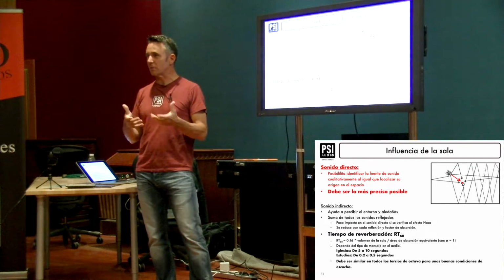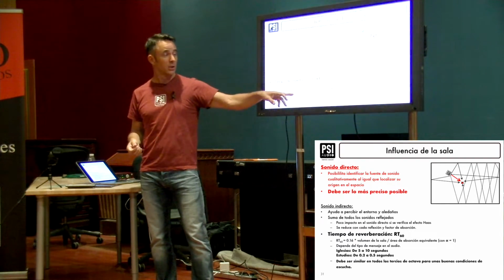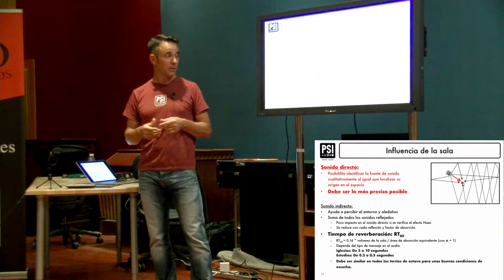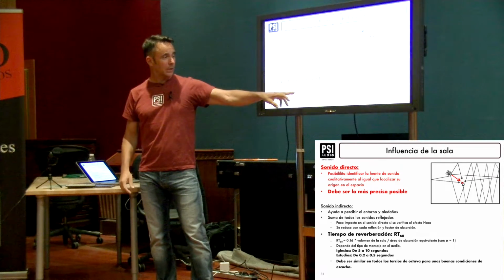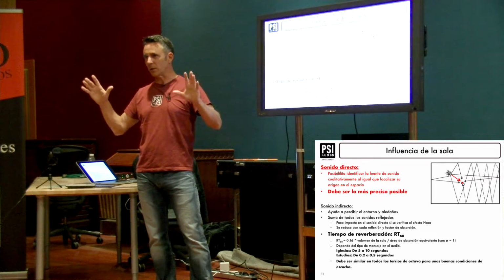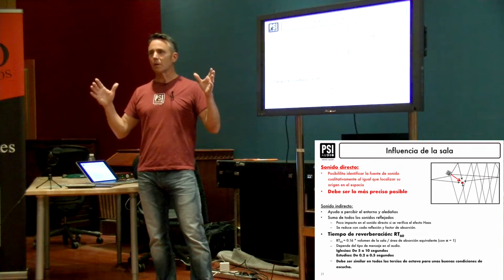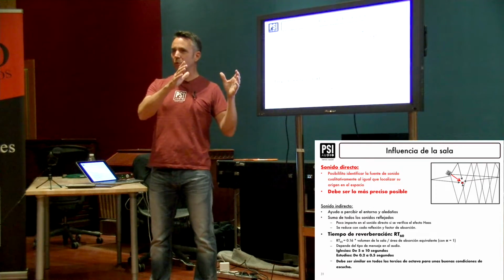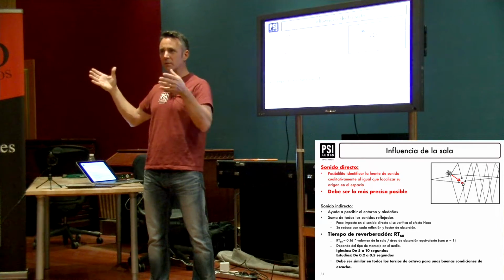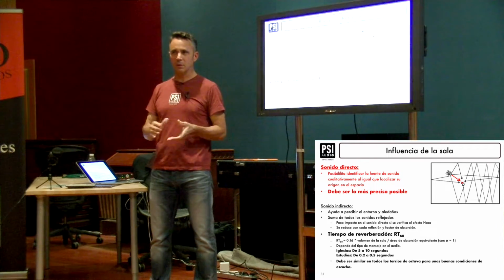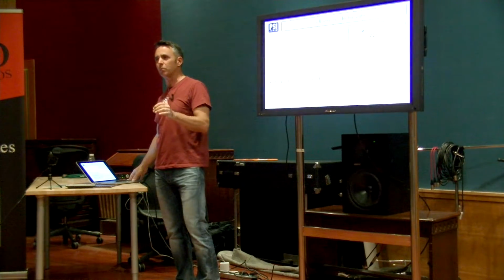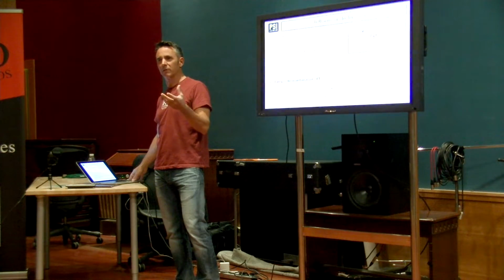In studios you have to have very fast music, and all types of music, so you want the reverb time to be extremely short so that you can hear the next sound that's going to come. Very simple. But what's important is that you have approximately the same reverb time in the low frequencies and high frequencies. We'll see that it's very difficult, but you don't want to feel as if you're in a cathedral with low frequencies and in the mountains with high frequencies. That is very disturbing, and you get a lot of wrong information. So RT60 is the most important parameter in characterizing a room.